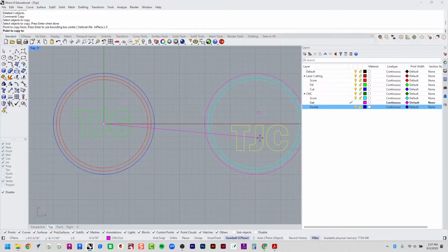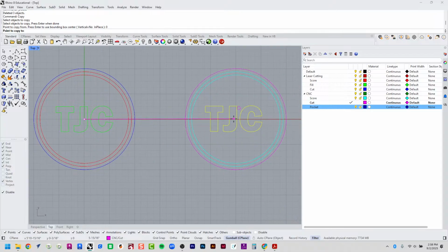And I would want to say, well, put it in the center here. I don't know what that point is. Because I use grid snap, I can count the ways. 1, 2, 3, 4, 5, 6. Probably say 6, comma 0. Yes, I could do that. Or I could just place it anywhere near and then move it in post using that align, using concentric. Or I can start to use my object snaps.